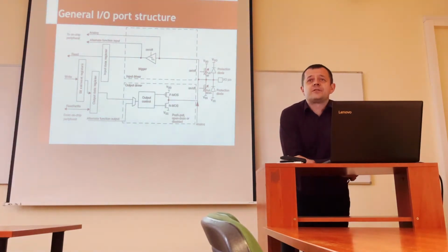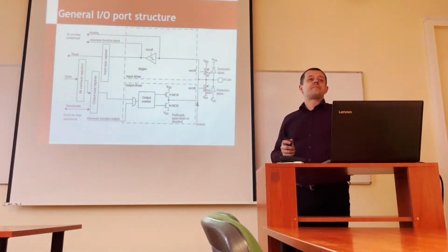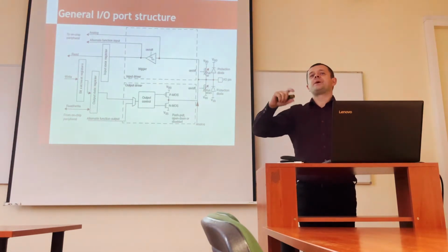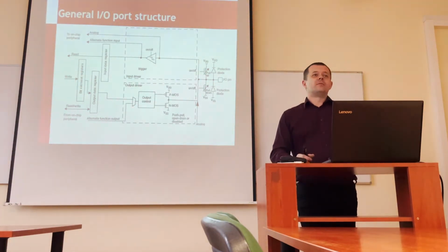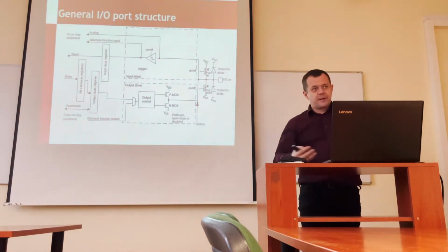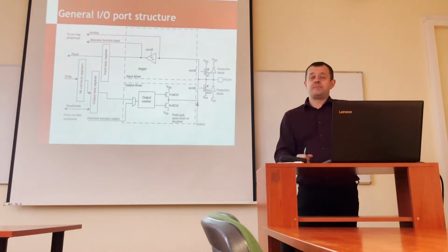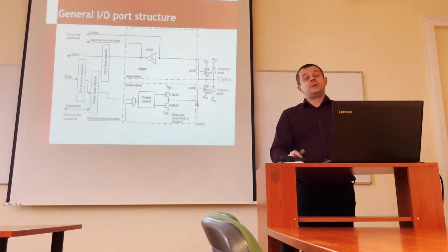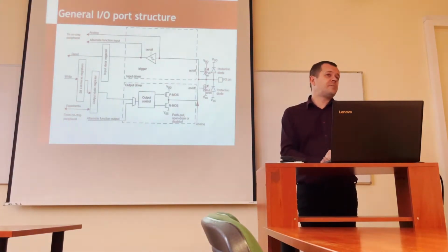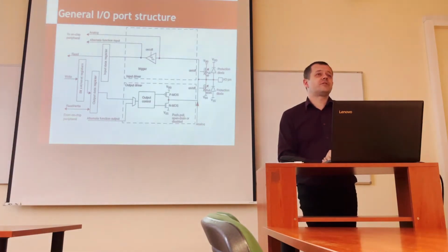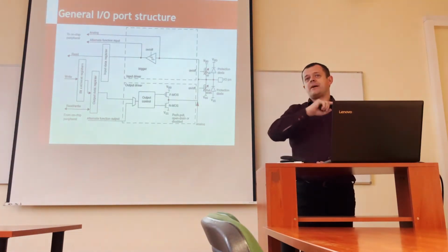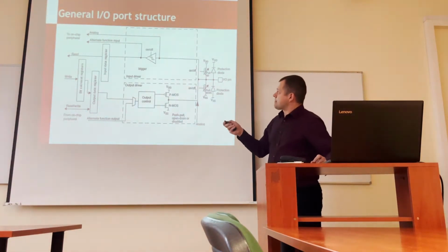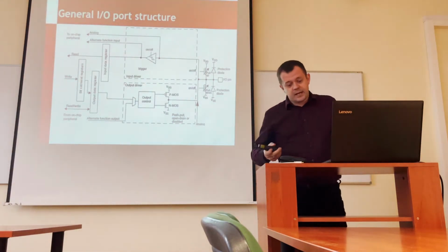Yes, of course. Because if we connect too many inputs here, the capacitance naturally will add, because parallel connection means that we simply add the capacitance. So 3 picofarads plus 3 picofarads plus 3 picofarads, then we'll end up with hundreds of picofarads. And this will limit the speed, the transition speed. So of course the transition will be slower. Instead of a nice square wave, we can expect a triangular wave or something like this for fast switching. So that's the limit in case of connection. That's why we usually don't connect 100 or something like this